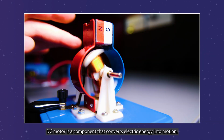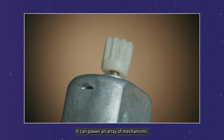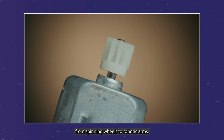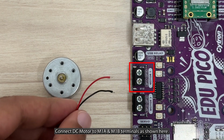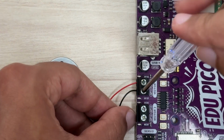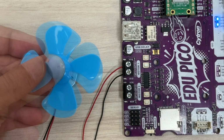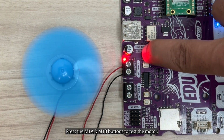A DC motor is a component that converts electric energy into motion. It can power an array of mechanisms from spinning wheels to robotic arms. Connect the DC motor to M1A and M1B terminals as shown here. Press the M1A and M1B buttons to test the motor.